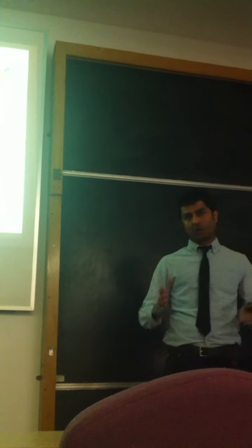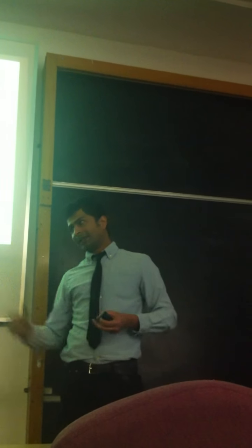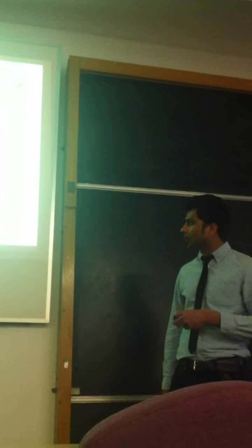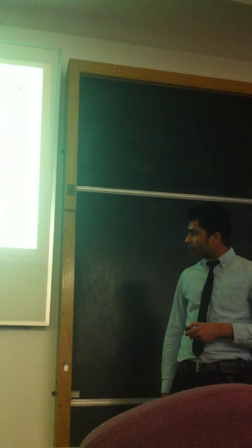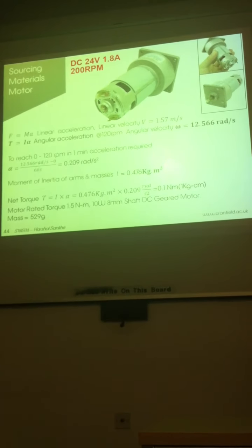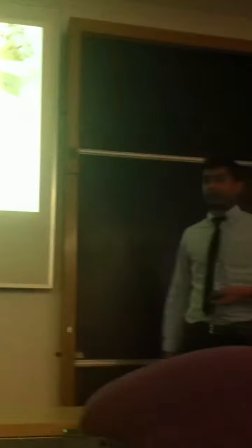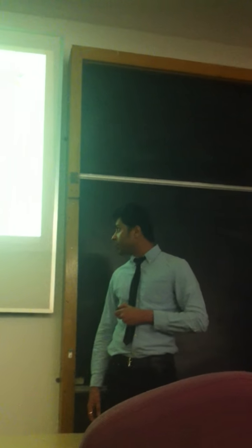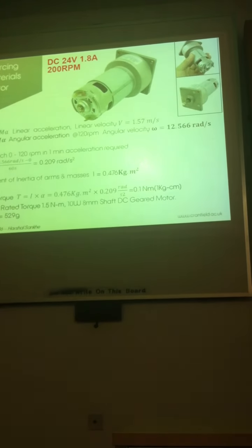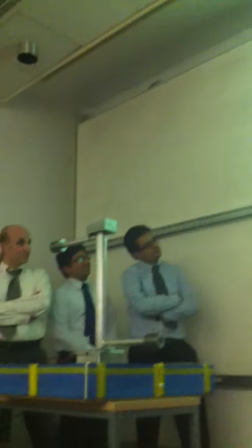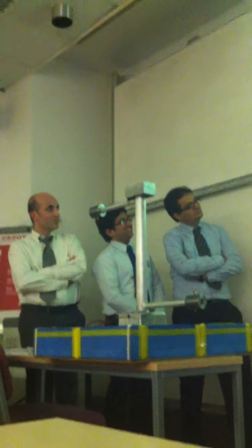The total mass had to be under 5 kilograms. Considering the arms, shaft, and masses, the motor had to be under 1 kilogram. So finally we found a motor which was just 529 grams. It had really high torque, and we were quite happy with it. The drag force calculated was very minimal, so it was quite okay to go ahead and source this motor from China. Thank you to our department as well. It was very quick, and we got this motor in 5 working days.